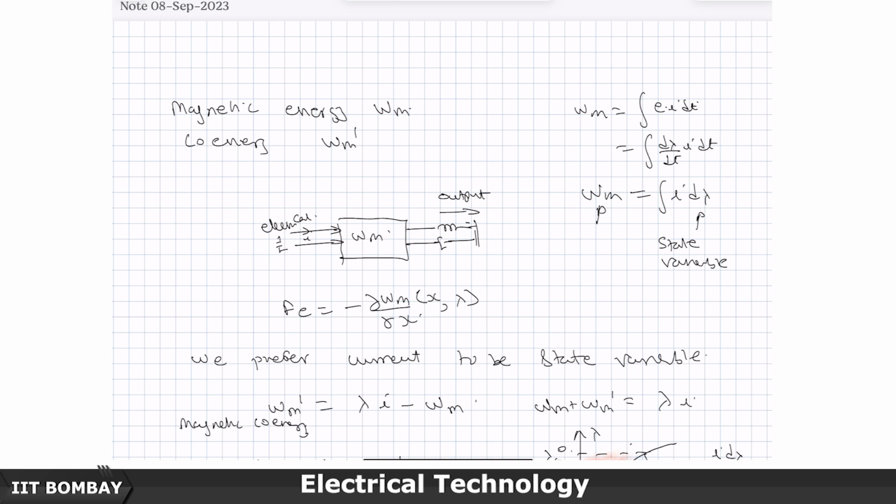I mean, we are considering it as a lossless, conservative system, because losses we will always try to keep down to a small fraction through proper mechanical engineering and so on. So, that small electrical energy which is being pushed into the system will either be stored as magnetic field energy, part of it, and part of it will be used to do work.